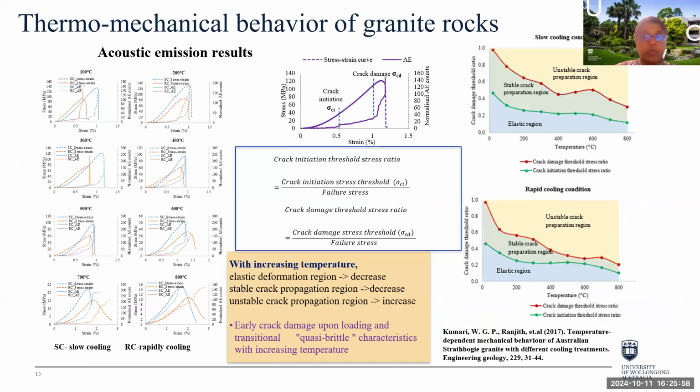We also used acoustic emission detection technology to study crack propagation processes in granite under high temperature conditions during shearing. We know that when a brittle material is under stress, strain energy is released during the development of new cracks or widening of existing cracks. And we can capture this energy release using an acoustic emission system.